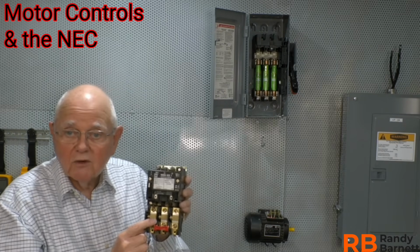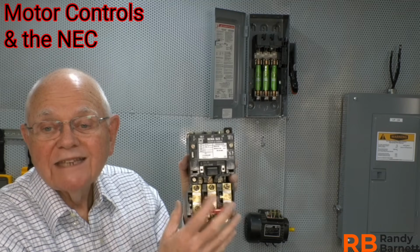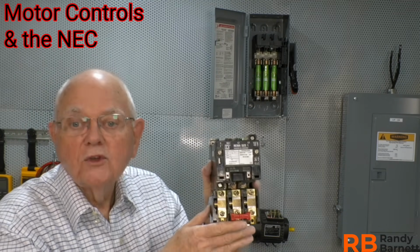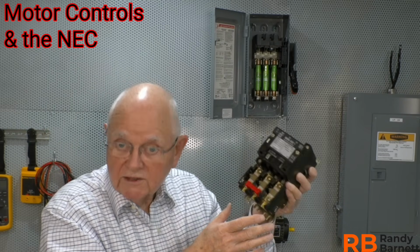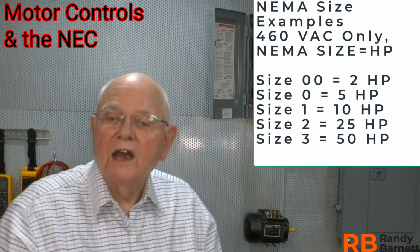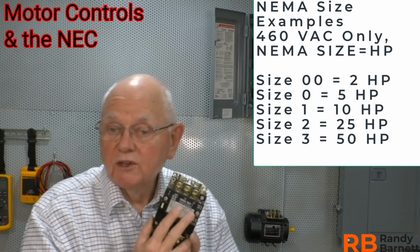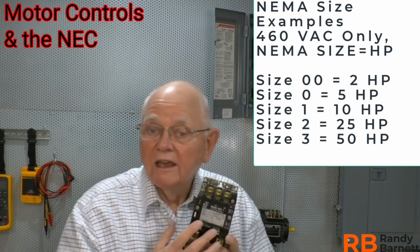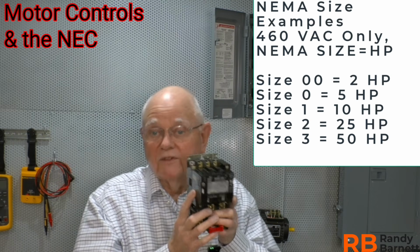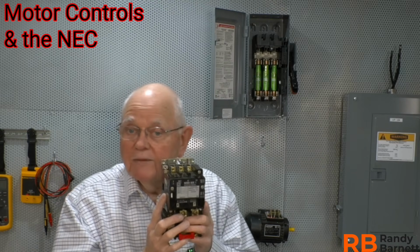On the bottom of the motor starter, I have these overloads, one for each phase. When I combine the motor overloads with the starting contactor, the whole unit is called a motor starter. So this is a NEMA size 1 motor starter. Now, if you're using IEC equipment, it's not sized per NEMA data, is it? So you have to look on the IEC starter and see what the kW, amperage and voltage ratings are for that particular starter. So that's my main power circuit.